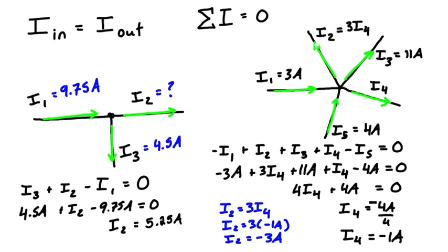So what we could do is update the arrows here, just like this, and turn them facing inwards. Or to make it even more clear, we could even change the color that we've updated it. And then when we label on the actual current, we could say that it is positive 3 amps flowing in and positive 1 amp flowing in. Or if you left the arrows pointing out of the node, you would have to leave the value as negative. Either of those would be totally fine, because either way it is basically just indicating that the sum is equal to 0.